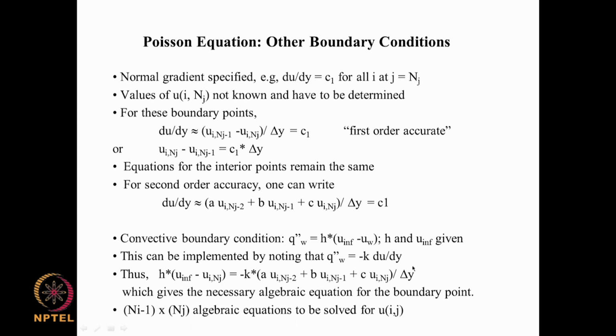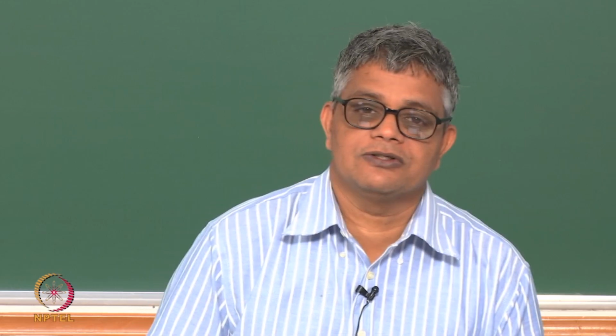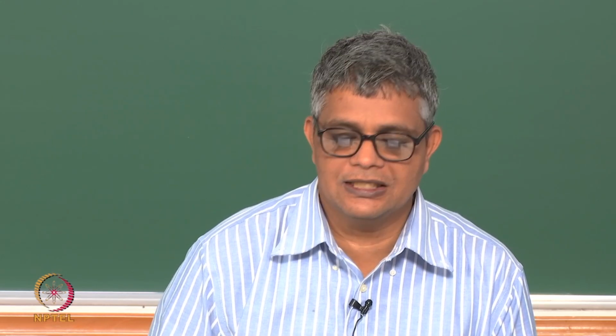In the case of a convective boundary condition, we had a slightly different form of discretized equation for the boundary points. So in this way we have seen that making use of finite difference approximations, we can convert a partial differential equation into a set of algebraic equations.